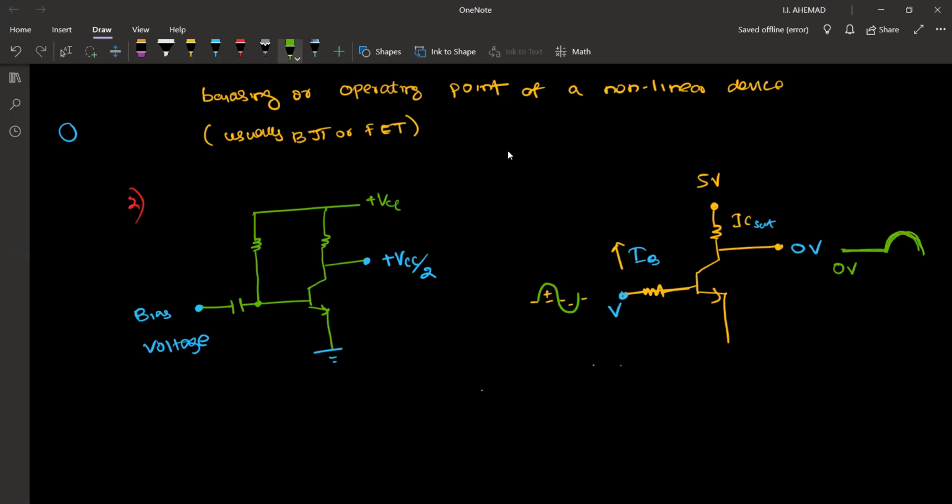So, is the idea clear? When you have 5 volts, that means if you do not bias, some part of the output is getting cut. And when it is biased, so we have the least voltage here, then also some part will get distorted. Okay, it is altered. So which will be the best value to set here? It will be 2.5. According to this, it is going to be 2.5.